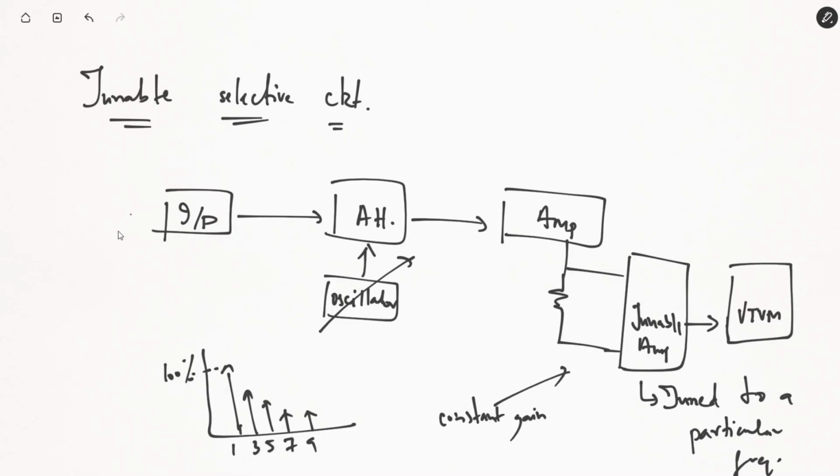In the second case, in which you want to measure the magnitude of all the frequency components, you set the attenuator to allow 100% of the fundamental frequency. We know that all of the harmonics are a ratio of the fundamental frequency component, so all those harmonics will be allowed. Almost all of the significant harmonic components will be allowed.